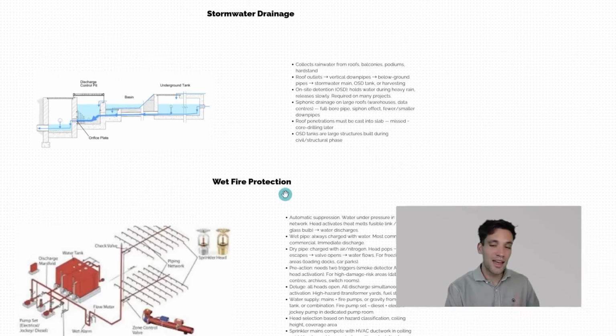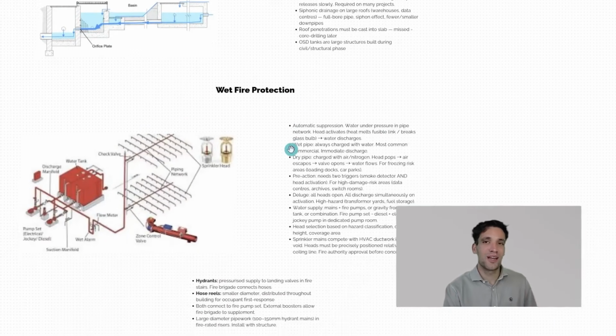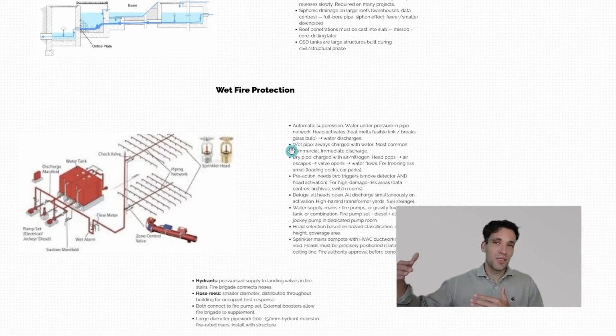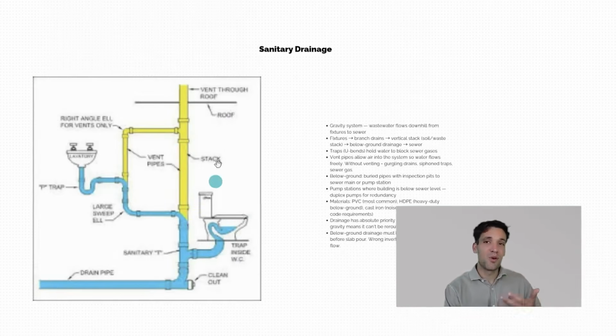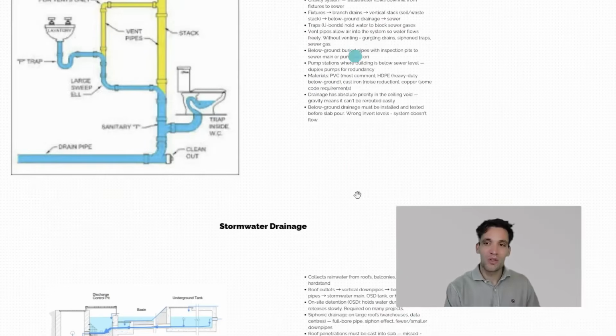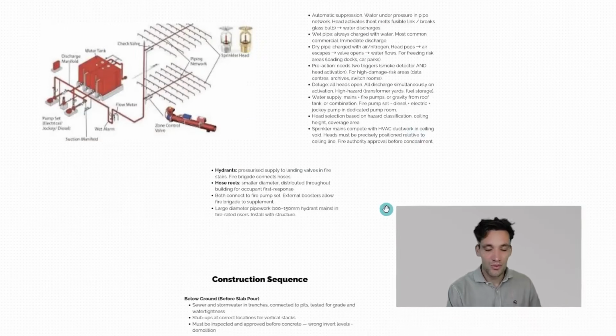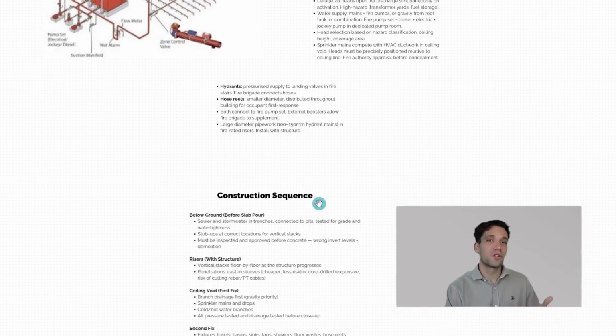And for all these services, it's really going to come down to 2 things. It's going to be measuring the lineal meters of pipework and reticulation, and then counting things like the number of sprinklers, the number of stormwater pits, the number of hot water units we have. Plumbing quantity takeoffs are very, very simple once you know what you're actually looking at.